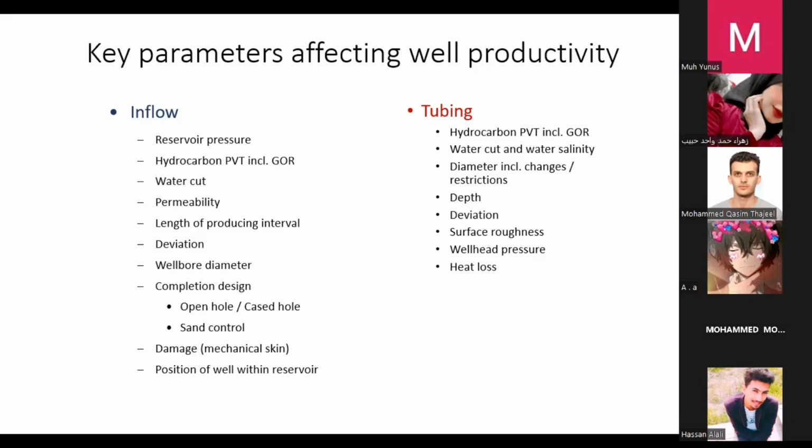The well deviation: in a vertical well, the interaction with the reservoir is less than in a deviated well. Wellbore diameter affects the inflow performance. If we have a bigger diameter, we'll get better performance. Completion design: it's open hole, a barefoot well, or cased hole.